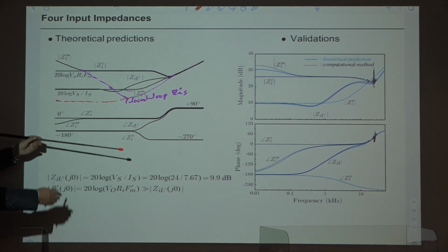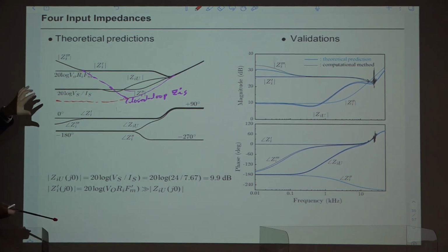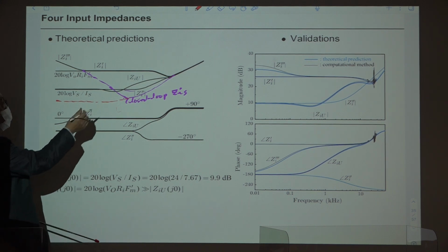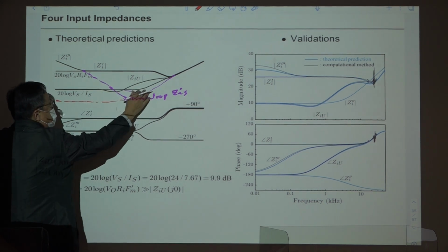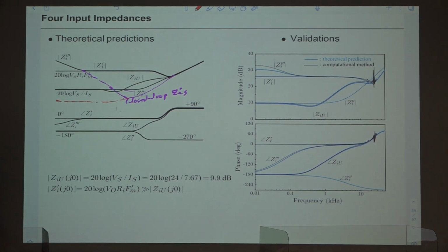So that internal current loop of current mode control boosts the impedance of these two during this frequency range. That makes the difference. So this is the benefit of current mode control coming from the internal current control embedded in current mode control. So that result is shown here.